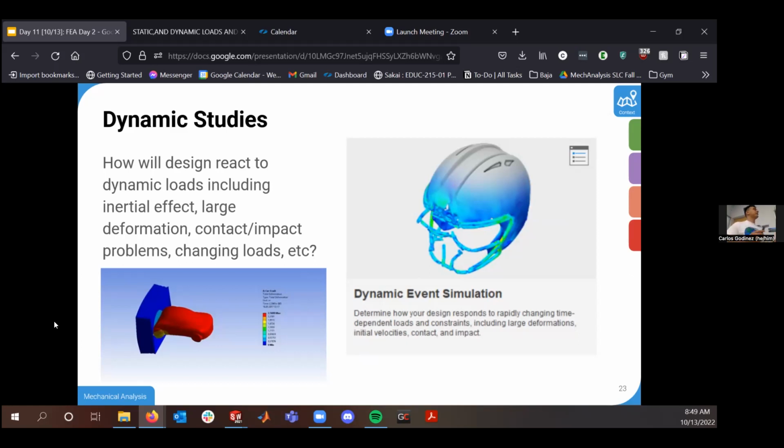The key question here is figuring out what my time step and what my time scale is going to be. We don't go into it, but there are rules of thumb for how big you want your time jump to be, because if you have too large a time jump your results aren't going to be that accurate, and too small a time jump, you're going to be using a lot of computational resources.